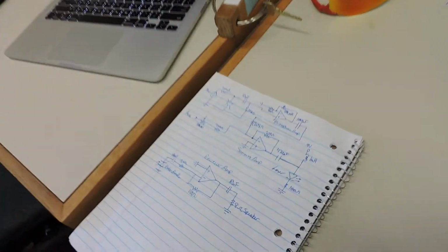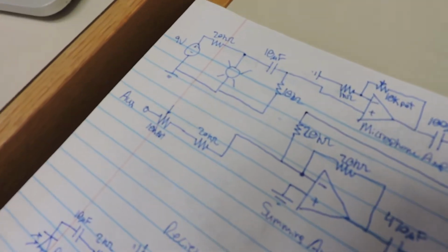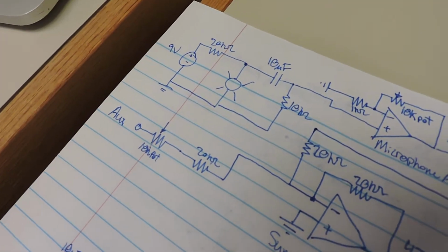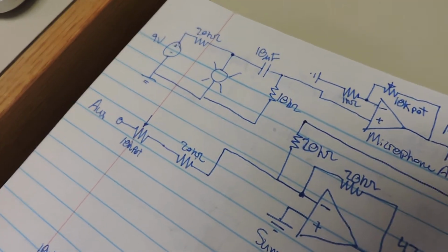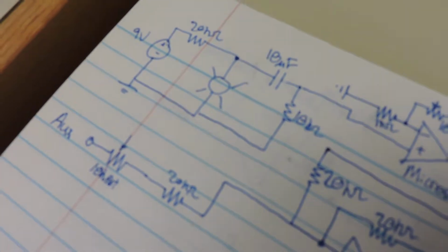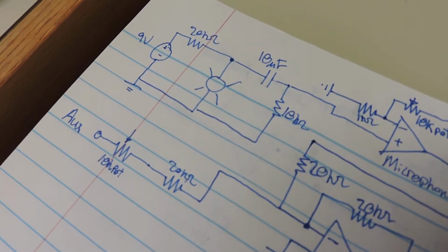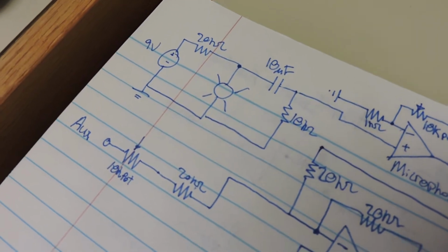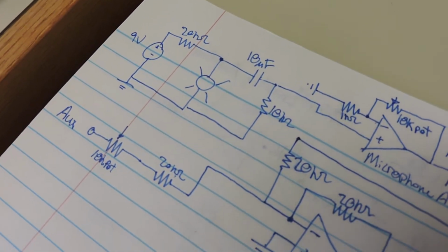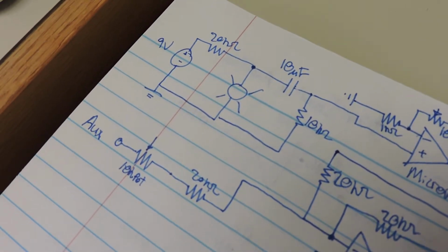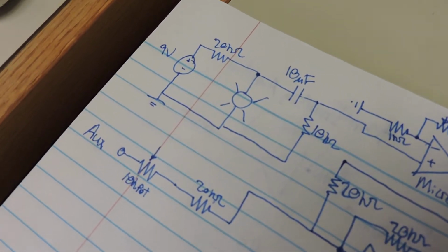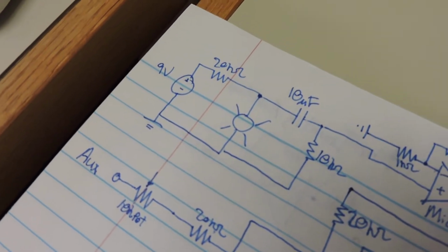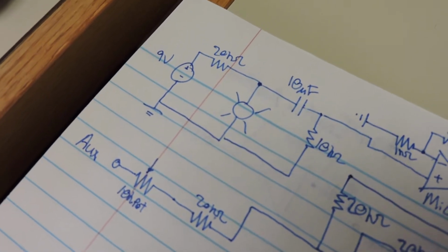So the microphone, which is shown right here, is powered by a DC current, and it creates an AC current when sound is played. So we use a capacitor and resistor in series with the microphone to block any DC current. The first thing that we did was measure the output voltage of the microphone, which we found to be 40 millivolts when the phone was 4 inches away from the microphone. This made us come to the conclusion that we wanted a gain of around 10 for the microphone to get the output to around 400 millivolts, which was what we measured for the auxiliary.